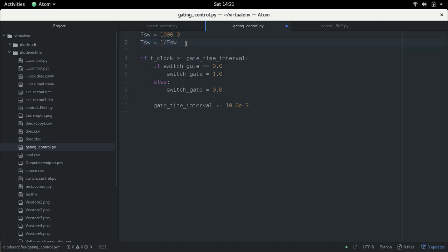Now, the reason I want to also show you this is because I believe this is not very easy to understand. In a simulation, we have the simulation time instant. The simulation time instant is the time step of your integration, rather the simulation time step. In this simulation, it is 1 microsecond. Now, usually you will run your control at a much slower rate. Most DSPs will run in milliseconds or maybe hundreds of microseconds. Typically, you do not run a control faster than your simulation time step because it doesn't make much sense.